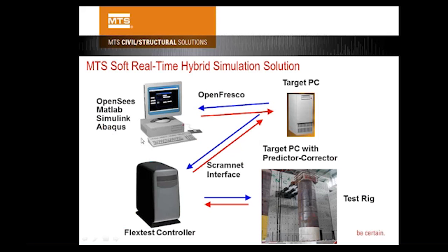So in this case, the analysis model software can be non-real-time software, like OpenSees. It runs in the Windows environment, and it doesn't know what real time is, so that's fine, as long as the model can be solved fast. So after solving, the command is sent through OpenFresco again, but to a target PC.